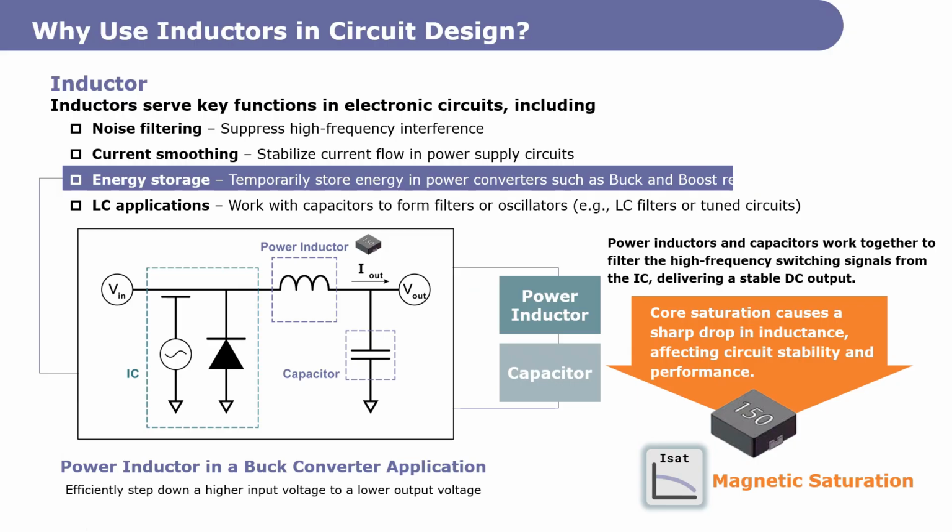As shown here, power inductors are used in switch mode power supplies. By rapidly switching the MOSFET and combining passive components like inductors, diodes, and capacitors, the circuit converts high-speed switching waveforms into stable DC voltage. At this point, magnetic saturation becomes a key concern.